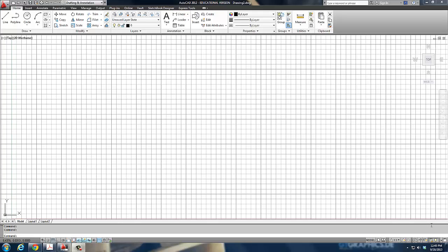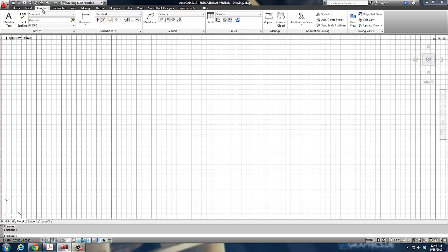Now, my desktop right now is white with a grid on it to draw on. Our pull-down menus are actually a ribbon bar at the top here. See this ribbon? This is where you select your drawing tools and things from, and you've got your home tools, it has your draw tools, modify, your layers, your annotations. Now, annotations, we'll show you some other stuff with it in a minute, blocks, etc. As you go down, you'll notice there's another box right here that says annotations. Well, this is another ribbon that allows you to do more detailed annotation information. So if I pull it up, it allows me to do more things, call-outs, bubbles, etc.